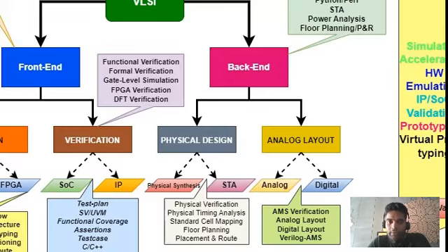That's the primary goal of having these things. We have the emulation platform, the prototyping platform, and the virtual prototyping platform. This is called the pre-silicon validation environment. Any chip industry must have this infrastructure before they go to the actual silicon environment.